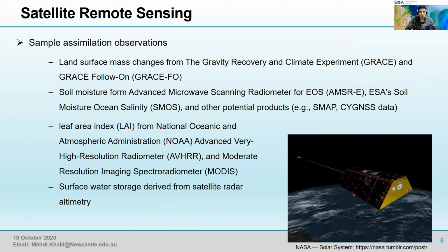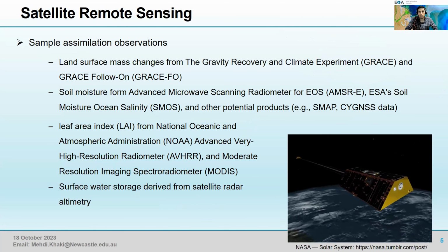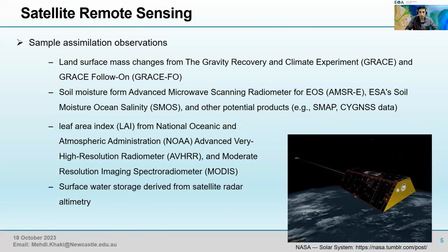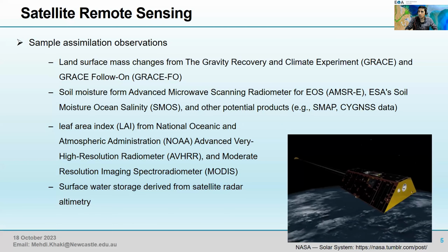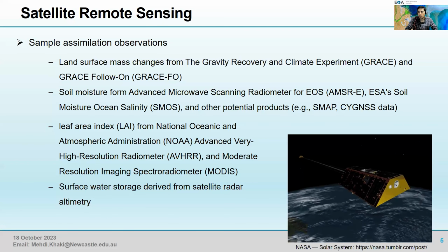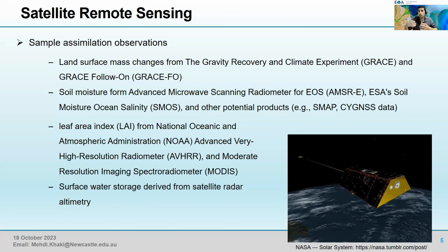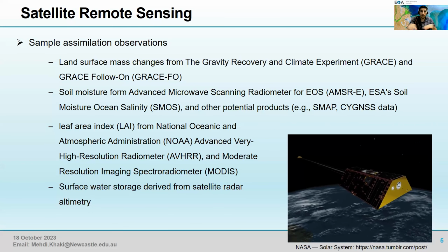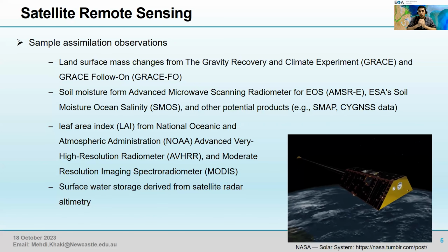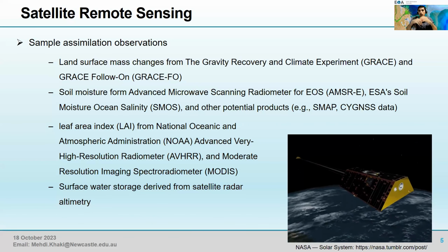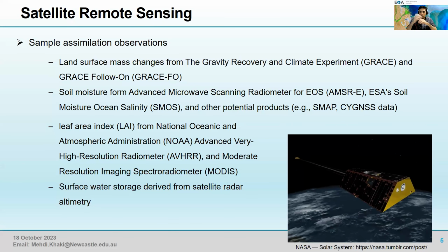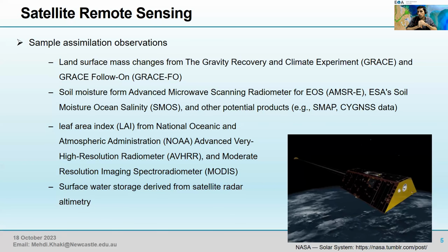Specifically over the land, this information can be very useful in quantifying total water storage changes, which can, again, be used to improve the model. So in a majority of my studies I've been using GRACE products for improving the water storage components. One of the advantages of using the model is that you can disintegrate the total water storage data that we get from GRACE into various components like soil moisture and groundwater. So we can improve those components while we get this kind of separation in the total water storage data.